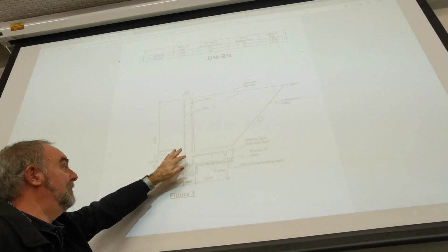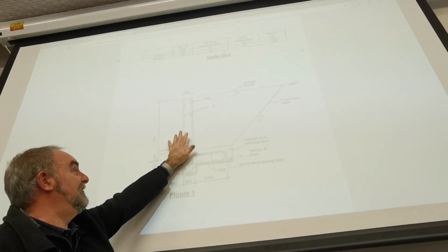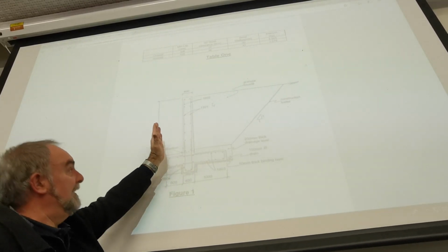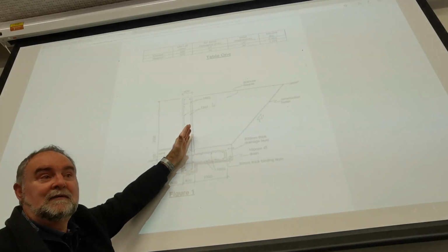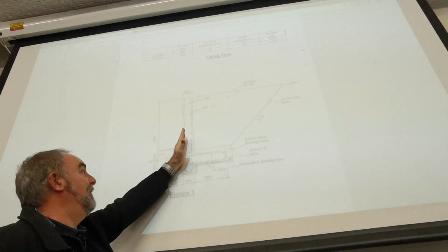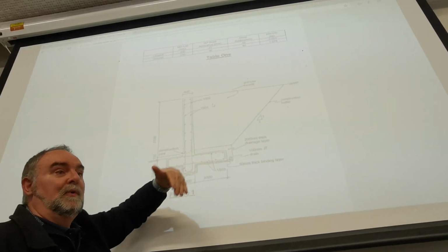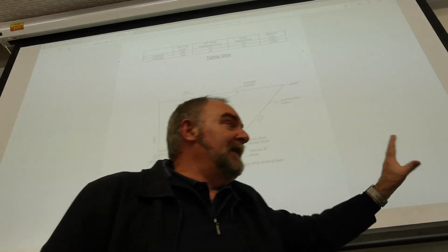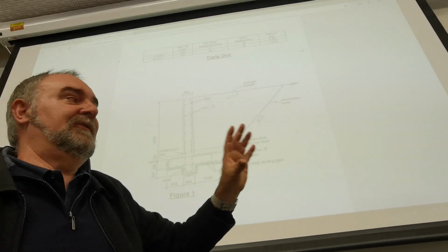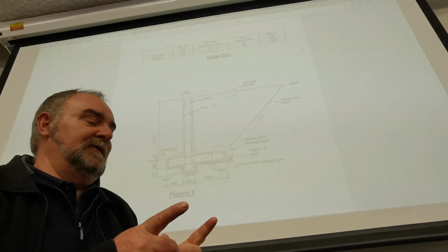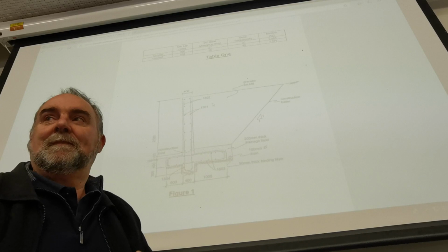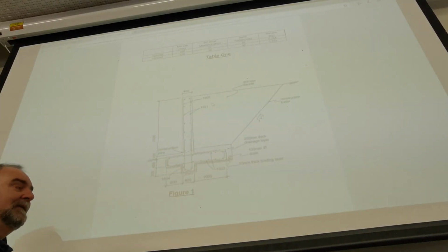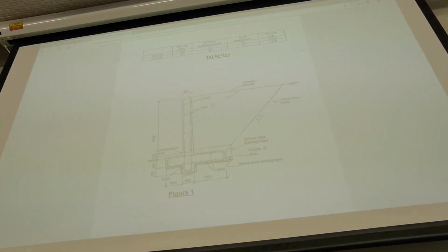All right. Now, normally on a retaining wall, the same steel is on both faces. But if it's on an angle, which some retaining walls are, then that would mean the front bar would be slightly longer. So therefore, it would be a different bar mark. Bar marks are only exactly the same bar. So if it's that much difference, it's a different bar mark. Okay. Sometimes, if there's an overlap, they might use the same bar mark and just overlap it a little bit more. But most of the time we call up a different bar mark. Right, so that's what that is.